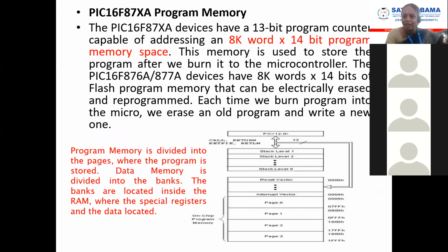How many deep levels of stack? 8 deep level of stack. And especially for the interrupt vector, this is 004. So 004 is allocated for the ISR routine.